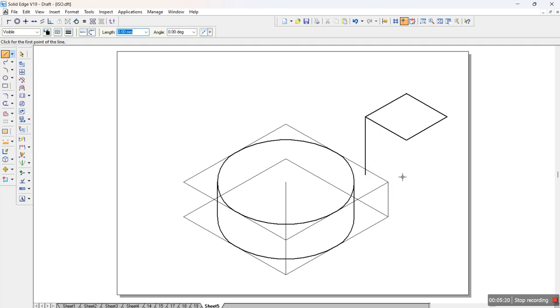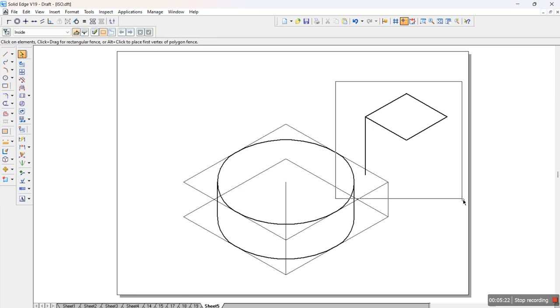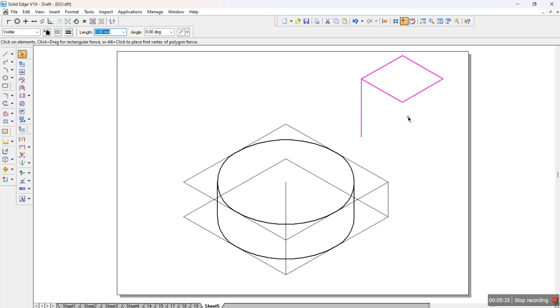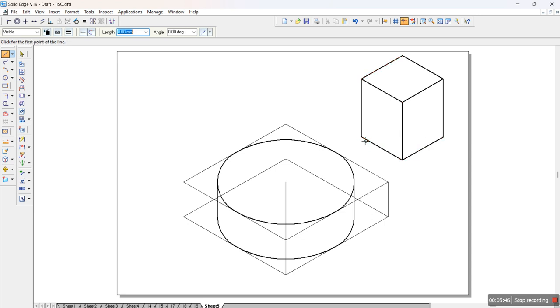So actually it overlaps out here, so we'll move this particular figure a bit upwards so that it's easy for us, and from here we'll move it downwards 50, and similarly from here we'll move 50 mm downwards. And make sure you draw the line straight, sometimes it happens. So 50, enter, connect the ends of the lines which have projected down. Now to find the center of this particular point, I will mark another line, so I will trim this particular area and this particular, so that this will give you the center point.